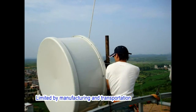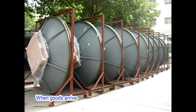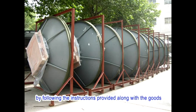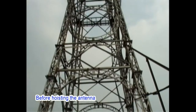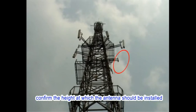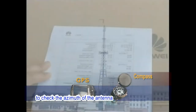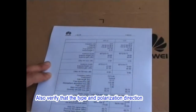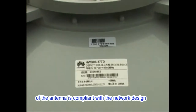Limited by manufacturing and transportation, large-size antennas are disassembled for the convenience of delivery. When goods arrive, you need to assemble the antennas by following the instructions provided along with the goods. Small-size antennas don't need to be assembled. Before hoisting the antenna, confirm the height at which the antenna should be installed. Use the compass or GPS to check the azimuth of the antenna. Also verify that the type and polarization direction of the antenna are compliant with the network design.